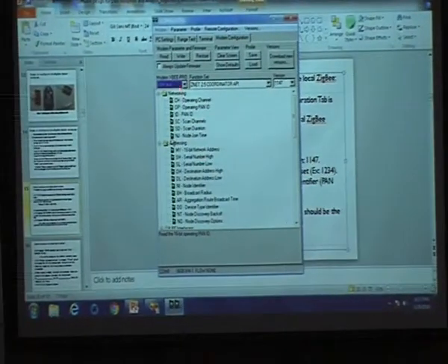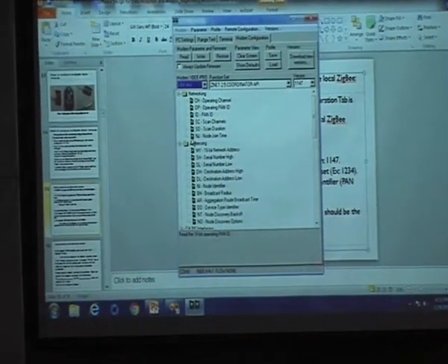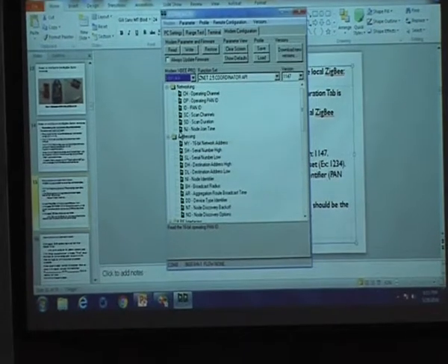So this current ZNet software provides the modem firmware for the newer versions of XB, SB and ZB. You will see only ZNet versions available for you, but in the older versions you will not have ZNet. So now this is the ZNet 2.5 coordinator API, and the version number is 1147. These three parameters are being selected here, and the corresponding parameter values for that modem type and function set need to be assigned in this particular screen.